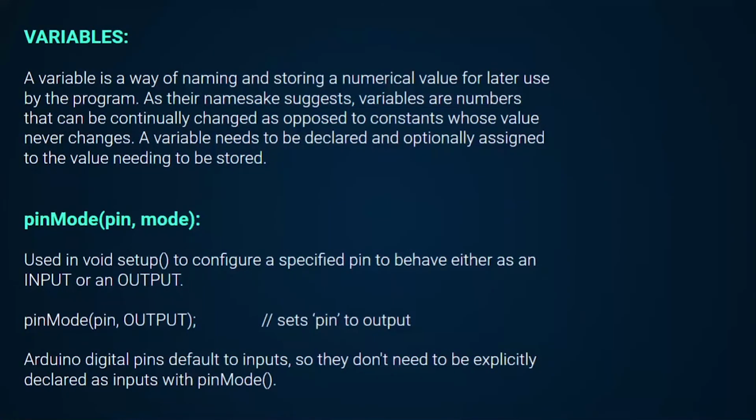One more thing is that the digital pins are by default input, so they need not be explicitly initialized with their input mode. So the pin mode function, as the name suggests, initializes the pin to a specific mode. The parameters passed here are pin and the mode.